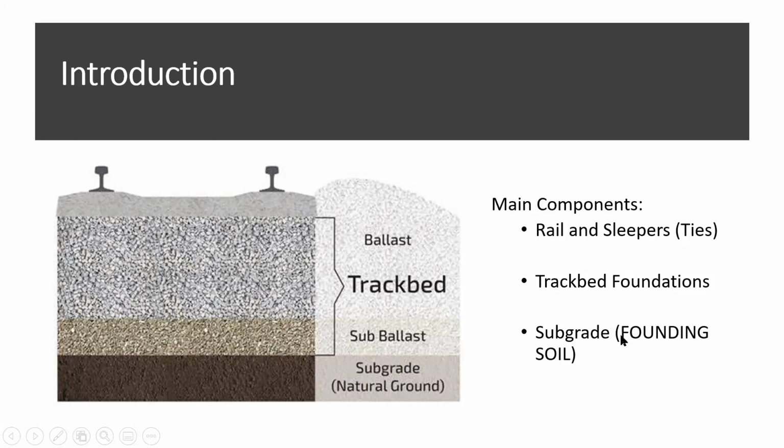And then your subgrade is basically your founding soil. One of the issues I always come across when I'm reviewing work by others is that sometimes you focus a lot on designing the track bed, but people tend to overlook how these loads will transfer into the subgrade. So always remember that your subgrade is your founding soil.